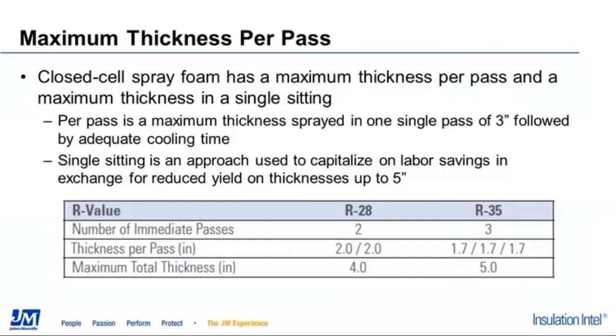This one is where oftentimes the foam looks fine on the way out the door. And then what happens is 2 hours, 6 hours, 2 weeks, or 2 years later, the foam starts to experience what's referred to as a dimensional stability issue. And one of the things that you guys should recognize is that when we spray the foam 1 inch thick in a single pass, and we're talking about we sprayed enough liquid that after the foam grew, it grew to be 1 inch thick, and now it developed a skin. The core density of that 1 inch pass might be 2 pounds per cubic foot.